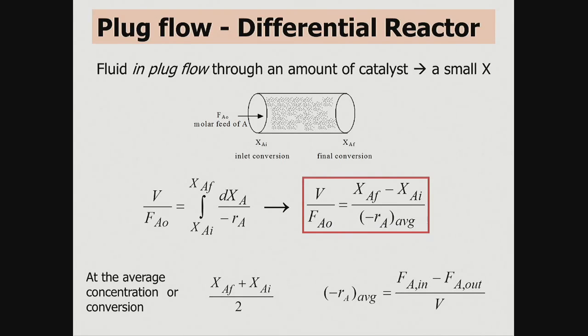So we try and keep the, how low do we keep the conversion? Well, as low as we damn well can keep it, but what's the problem? We're at really titchy conversion and we want to be at 80% conversion. So we're here with our little reactor model trying to get kinetics and we want to be over here. We're way away from the design parameter, but it gets some of the important kinetics out, which we can then test if we go to higher conversions. So we start simple, we go more complicated.